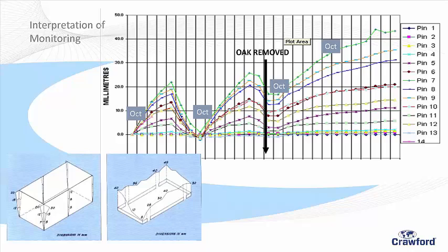So we might do other sort of distortion surveys. That's a level survey. Here is another type of survey called a line survey, a plumb bob survey, to tell us what's out and what's in, because we can eliminate restraint problems as well. We do this because we sometimes do investigations, but we know damn well what's down there. We've got a catalogue of about 20,000 to 30,000 investigations in there.